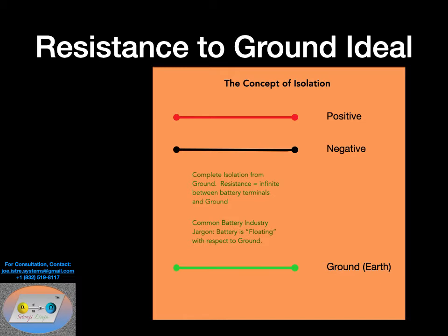By the way, if you're evaluating a battery system and if anyone connects a ground to the battery terminals of an energy storage system, my recommendation is don't do business with them, because that's an extremely dangerous system and you don't want to be anywhere near it. Okay, so here we have the three terminals, and ground's not connected to either the positive or the negative terminals.